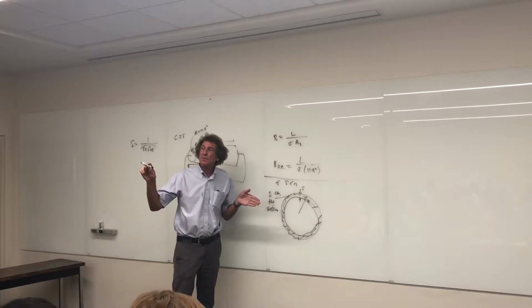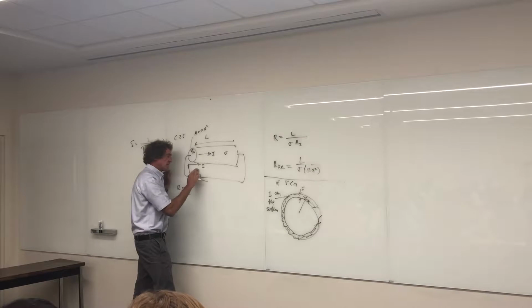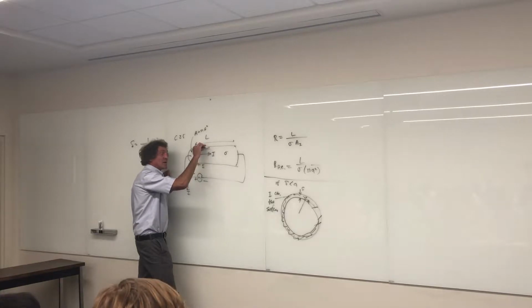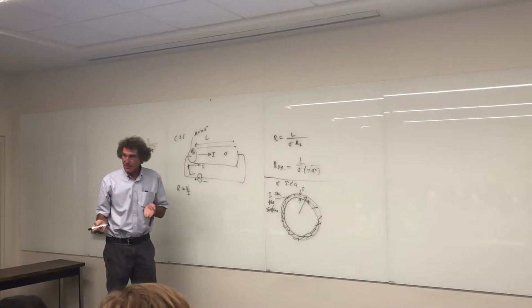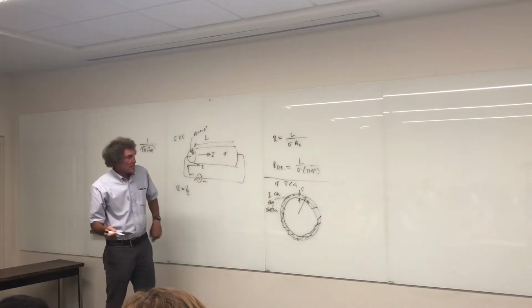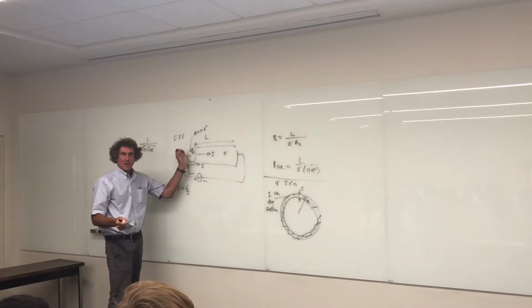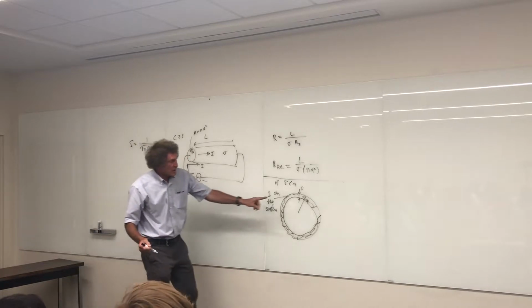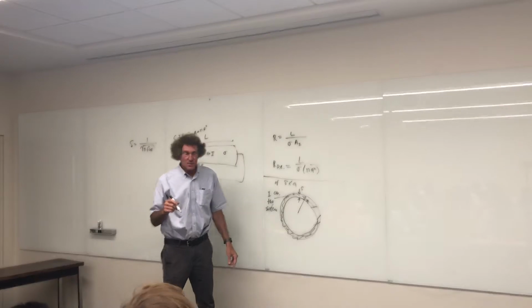When you have an electric field like this, it's in this direction, but if it's not a DC voltage, if it's a time varying voltage, and you get a skin depth, all the current flows this way. As it tries to propagate towards the center, it gets shorted out because of the skin depth effect. Are you with me, class? What that means is that it looks like a hollow wire. The current is only going to flow in the area 1 skin depth deep in the wire. Got it? So what is that area?